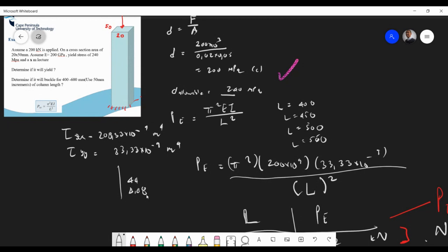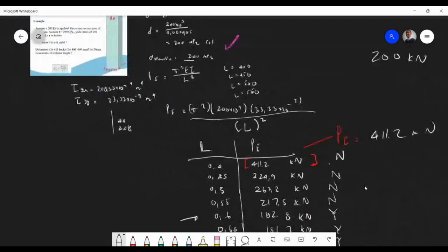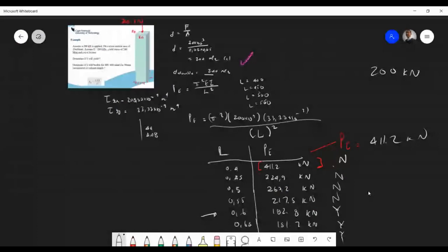So I really have no rule here. Anyway, yeah. But the concept, are you with the concept that even though your column can withstand the stress, it will buckle? It can buckle. So hope everyone got that. This question is just a concept question. That's basically all, so that you understand the concept of what buckling is.